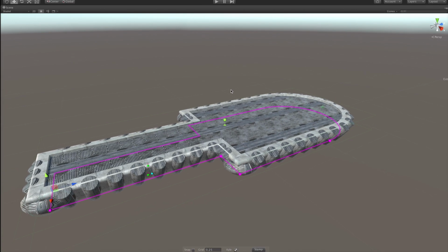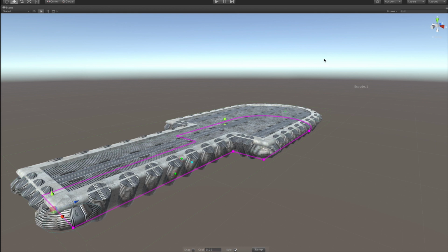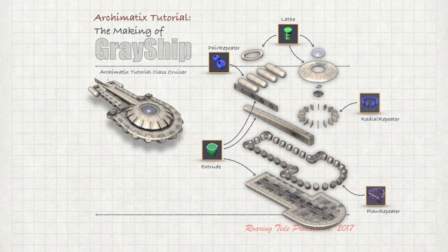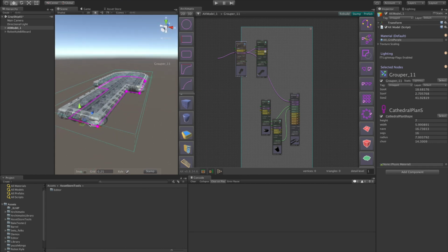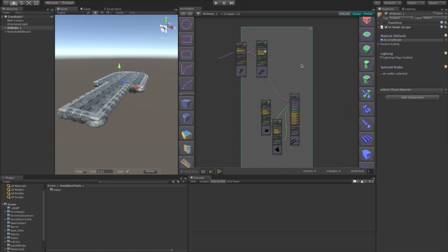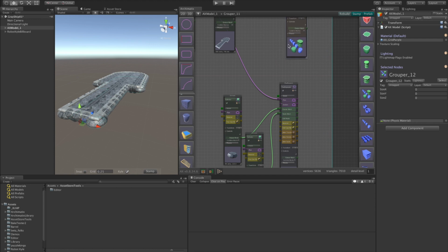And next we'll think about the round part in the front, the saucer. If you recall, the saucer is located in the front of the spaceship. And since all of these objects are concentric, it would be great to be able to create them in a new coordinate system that's located in the front of the ship. Our current center is in the back of the ship. But if we create a group and move the group to the front, then that will be our new theater of operation. So I'll just click on the group icon.